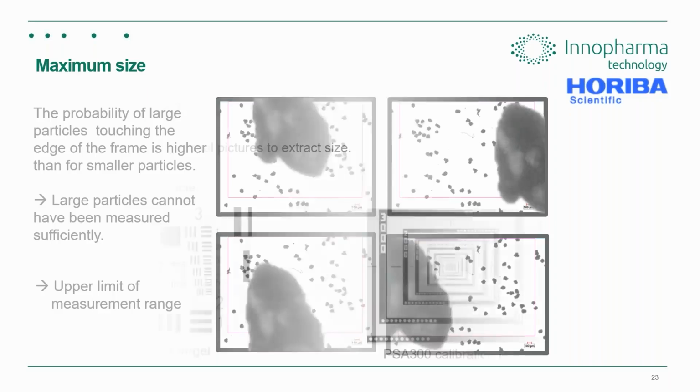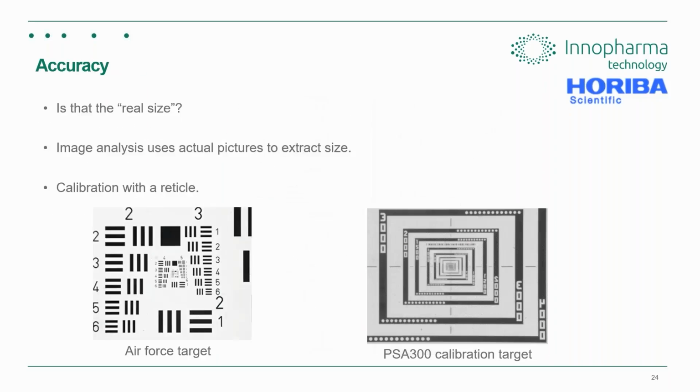So that's maximum size. If we're talking about accuracy for image analysis systems, because we are essentially taking photographs, you can use reticles or artifacts. If we look at the bottom left, we're looking at the United States Air Force resolution test from the 1950s, still used today for optical systems and vision-based systems for defining resolution.